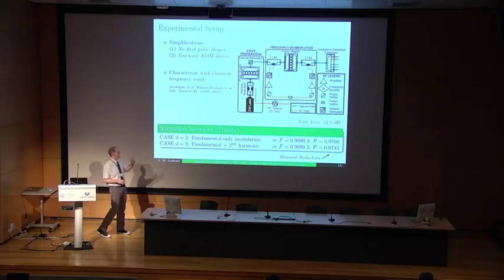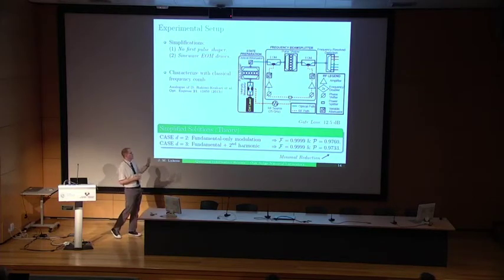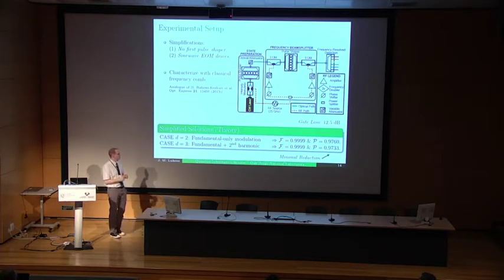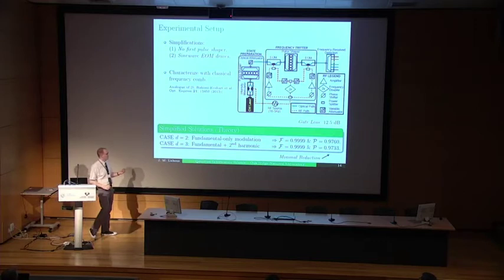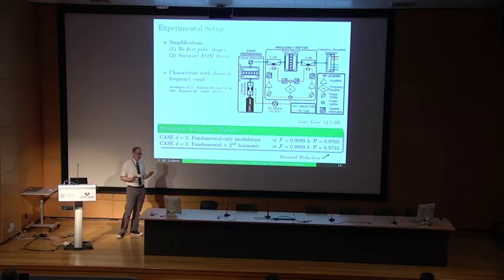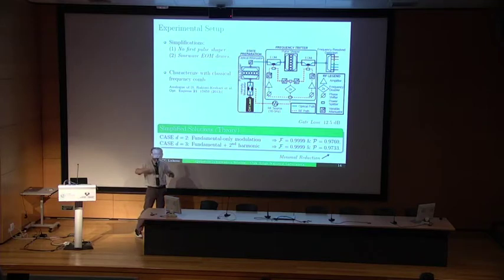And for these experiments, we use a classical frequency comb to do the probing, and we can attenuate it to the single photon level as well. So that allows us to create superpositions of these different frequency bins. And to go to the trigger, we found that we do need slightly more complex RF components. So a single frequency was not enough to do a high fidelity, high success trigger. But if we add the second harmonic RF component, we can actually perform very well. So here you can see we have a frequency doubler, and in the trigger case we work at an 18 gigahertz mode spacing so that we have a 36 gigahertz tone that we add with a particular phase with our 18 gigahertz signal as well to get the specific waveform we need for the trigger.